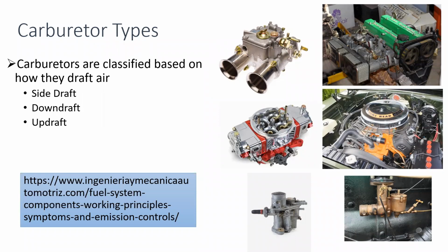Same here, you have one single carburetor. Let's assume this is a four-cylinder engine. It's feeding 4 cylinders, so there's no way of telling that all 4 cylinders are getting the same amount of fuel. So that's why for these sorts of setups, a separate carburetor was fitted for each cylinder, but it was a very complicated system, and tuning was also very difficult because there are different screws and different air bleeding systems. Everything has to be perfect in order for these to run. So this is not common.